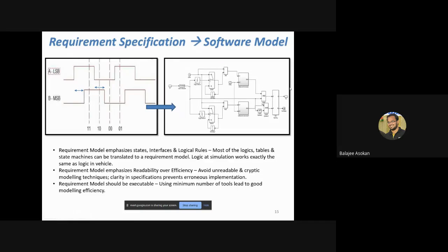Whether we have developed this correctly will only be known when you validate. But to ensure that we have actually completed this requirement, we can tag the requirements in the Simulink model. That process is what we call requirement tagging and traceability.